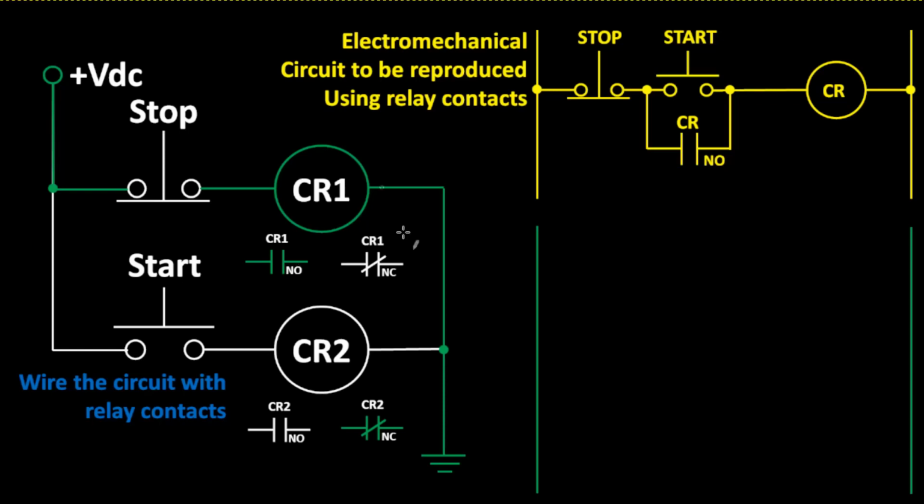Now, I have to know this status out here. In order to program PLC logic, you must know the status of the field devices. I'm going to repeat that. In order to build and program PLC ladder logic, you must know the status of the field devices. I need the first instruction or the first contact on my PLC start stop rung to be closed when nobody is pressing the stop push button.